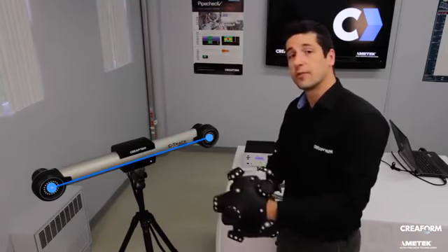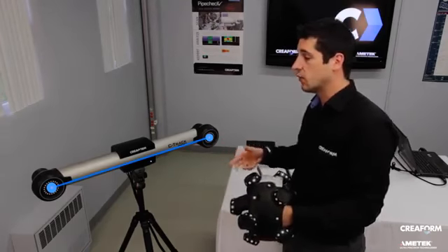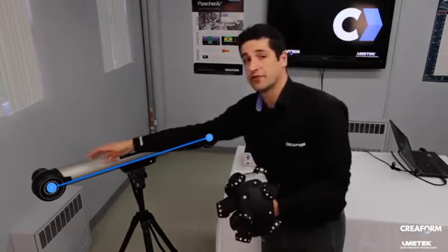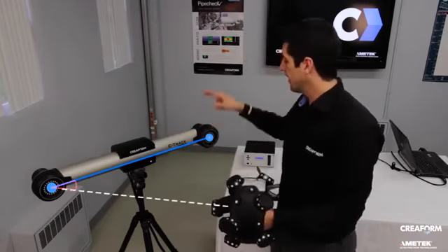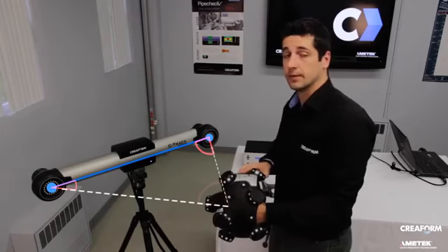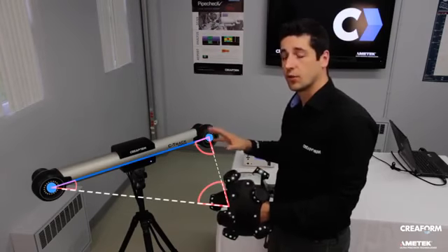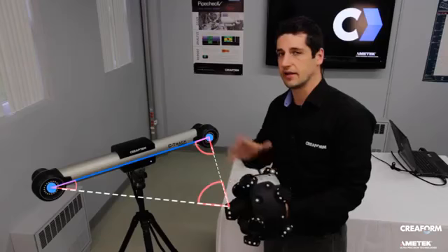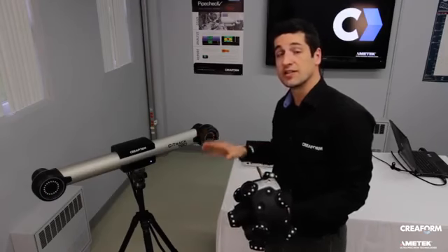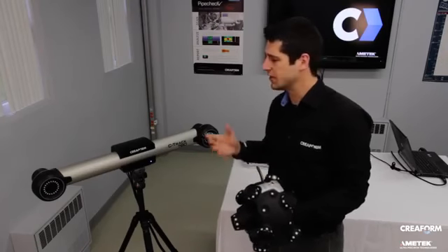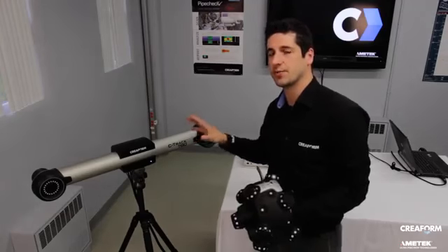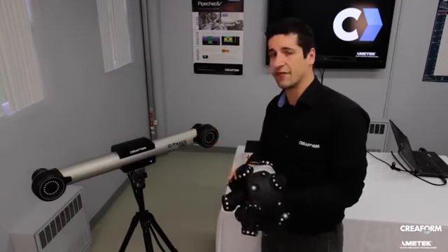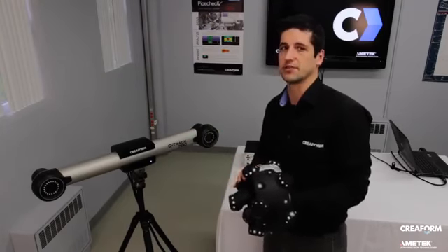Every time we move the MetraSCAN in front of the C-track, we can get the angle formed by the first camera to the MetraSCAN and the angle formed by the second camera. With all this information, we're able to position the MetraSCAN in space. Also, the C-track works at 30 Hz, which means it's taking 30 measurements per second. So we really have live tracking of the MetraSCAN position.